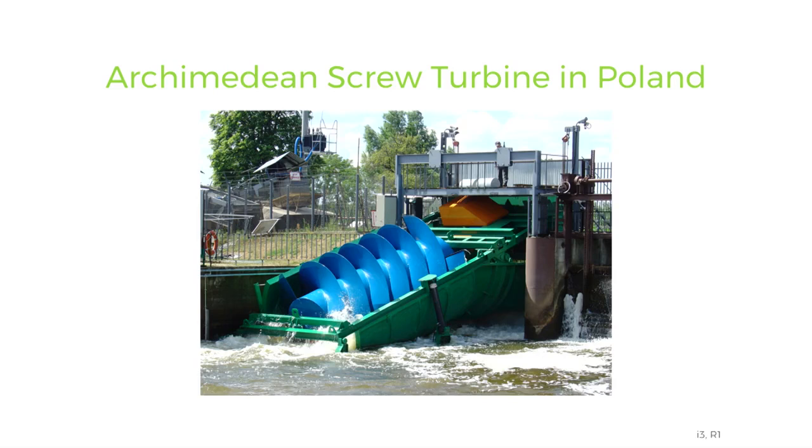One of the examples of low head turbine design includes the Archimedean screw turbine, which can be applied in 1 to 10 metre head difference and low flow rates of between 0.01 to 10 cubic metres per second. A study in 2007 estimates that the development of low head resources could nearly double the hydropower generation in the United States of America.